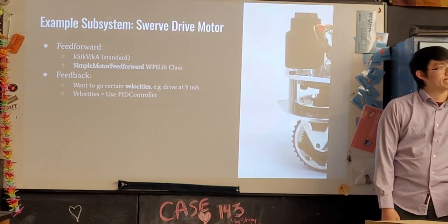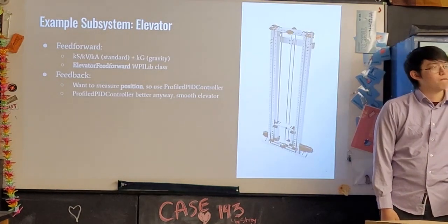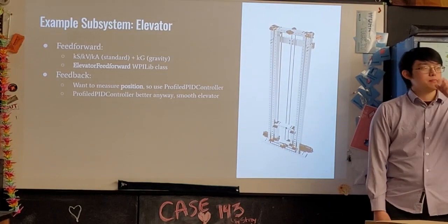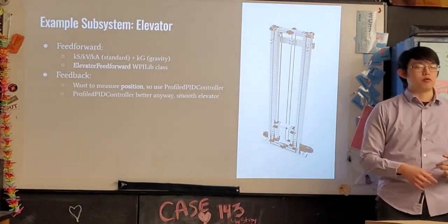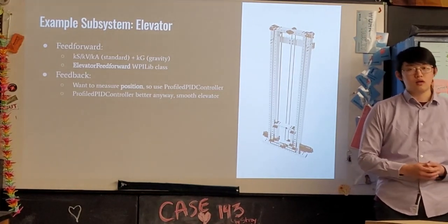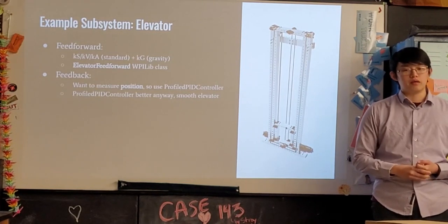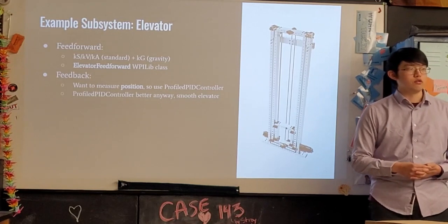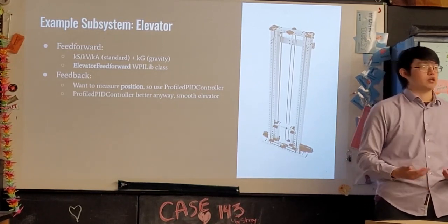But in the case of the elevator, did you have a sensor that detected that, or was it calibrated? How do you get there? Yeah, motor encoder output specifically. The Falcon 500s have an integrated encoder keeping track of the position and velocity. But for an elevator, you only care about the position. It has its own units, Falcon units, and you do a little bit of math, translate that into meters based on the gear ratios, chain links, whatever.